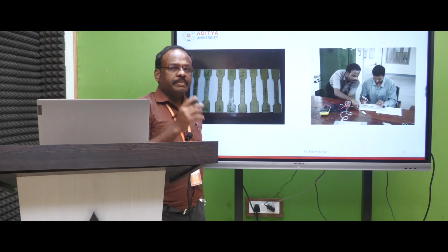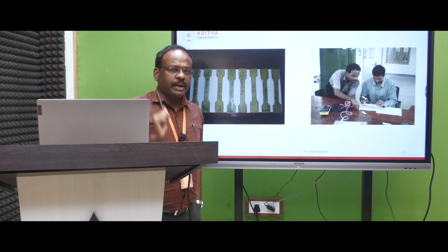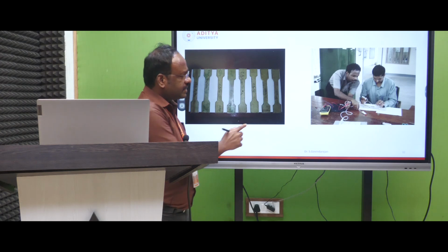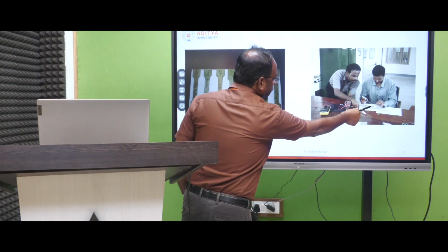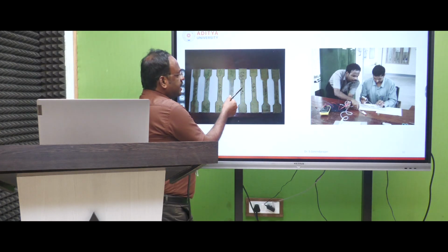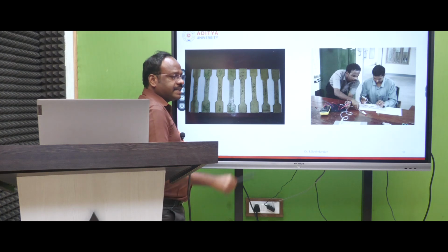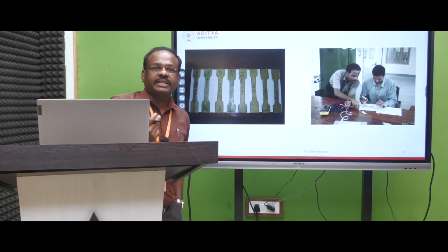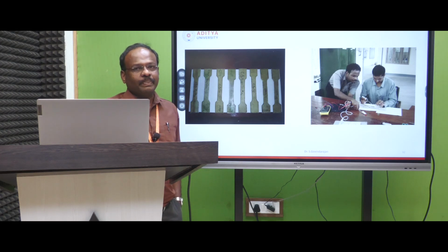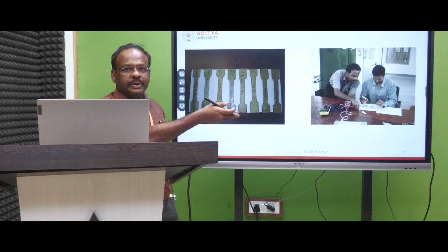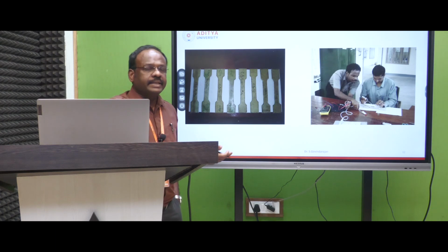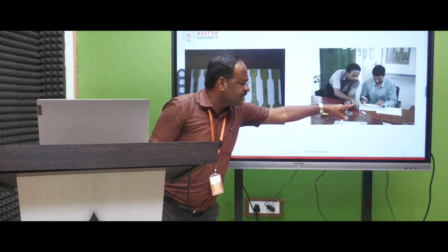Deformation. Okay, because you apply load in the tensile strength test, and where do we get the deformation value? By using a strain gauge. Here I place the strain gauge in the middle. So easily in the strain indicator you will get the digital value of the deformation, the strain value, right? Stress value is known from the area, and we give a load of 2 kilonewton, 4 kilonewton, for cyclic loading. At the same time you get the strain value from the strain parameter by using the strain gauge.